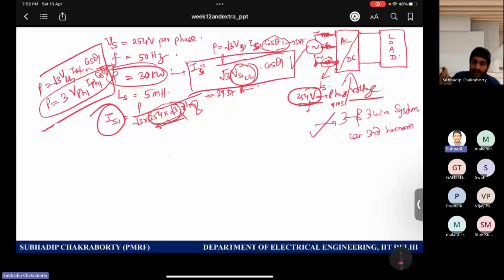So if you have any information about the amplitude of any one of the harmonics of that pulsed PWM voltage of the inverter, then you inherently know the information about any of the harmonic components.